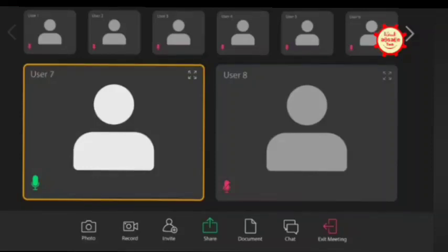No, I'm not talking about NACE alone. NACE generally doesn't give anything. I'm talking particularly about HIC testing. It depends on the severity, because if this equipment fails, what effects may occur? Accordingly they will classify the equipment. So I think mostly it should come from the licensor. We don't decide, but for NACE, it is given. We have to follow that composition, etc.